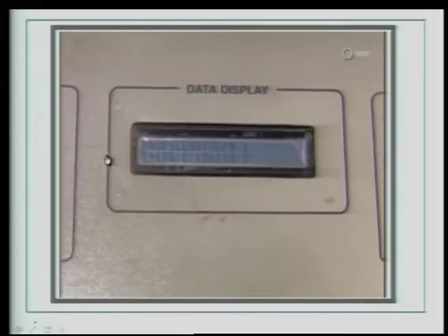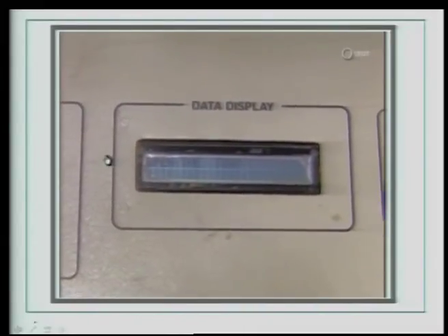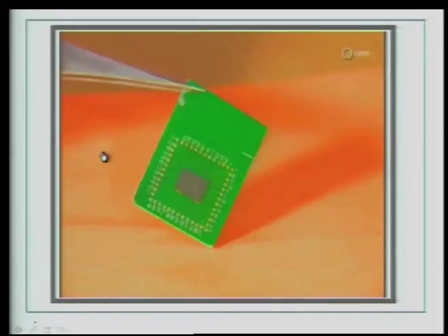Again, to avoid thermal shock, you should not remove the board from the tray and allow it to cool. Typically, you should allow it to come to room temperature as a natural process. So, this is a typical prototyping methodology that we have shown you that can be done for the reflow process using stencil printing.